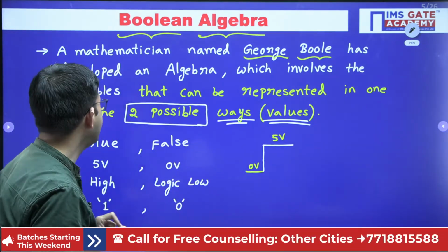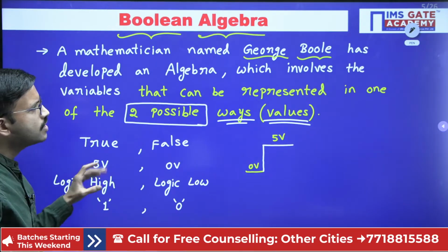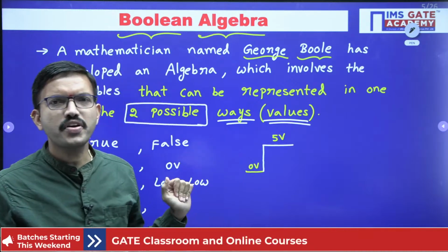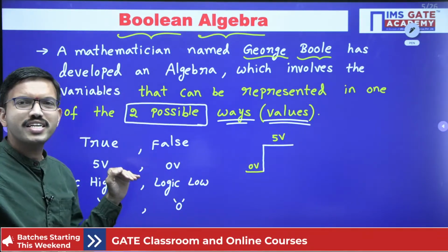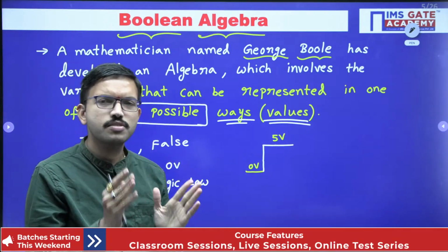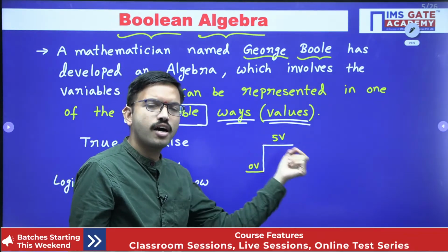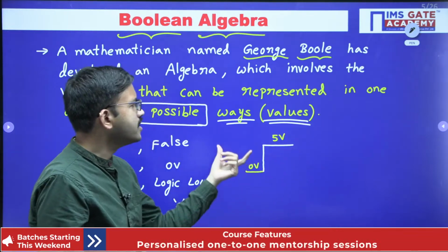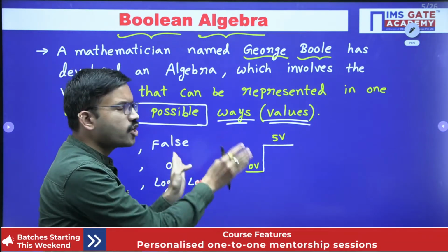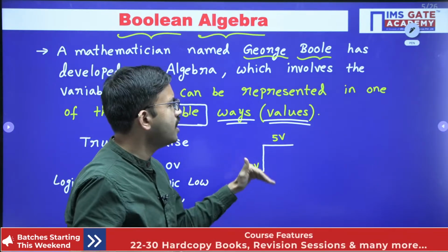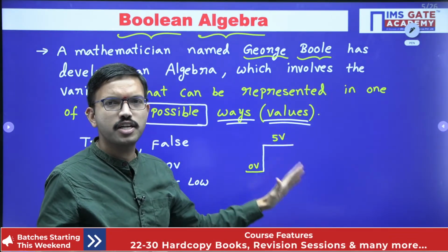Before going to discuss that point, whenever you want to design any circuit, especially digital, based on your required specifications you will determine how many inputs and how many outputs you require. Then you will write the input combinations in terms of zeros and ones, and for each combination you will write the corresponding output value, either 0 or 1.